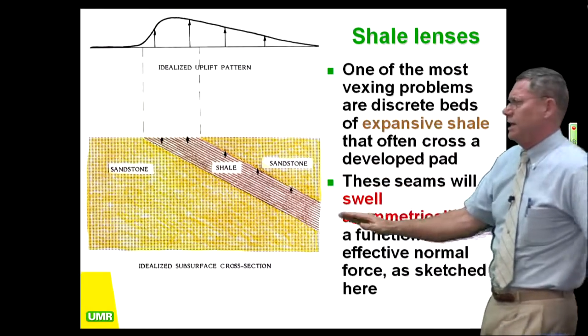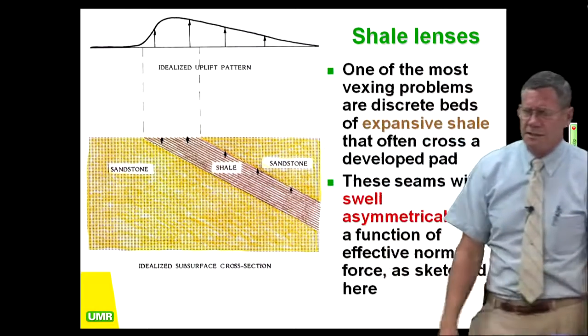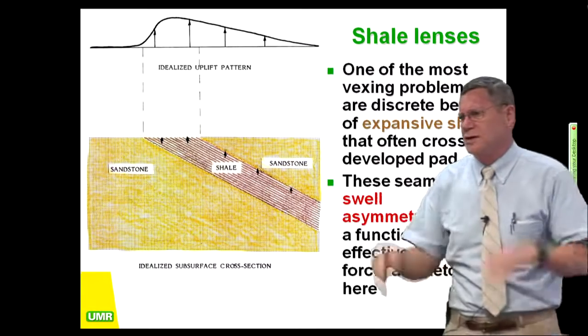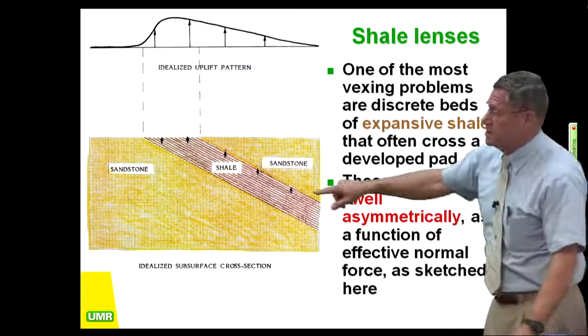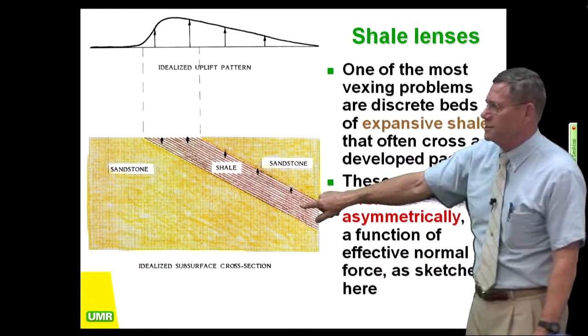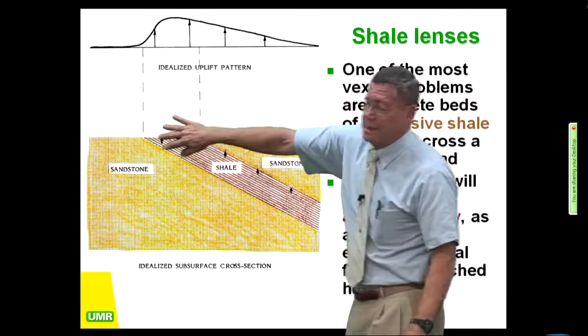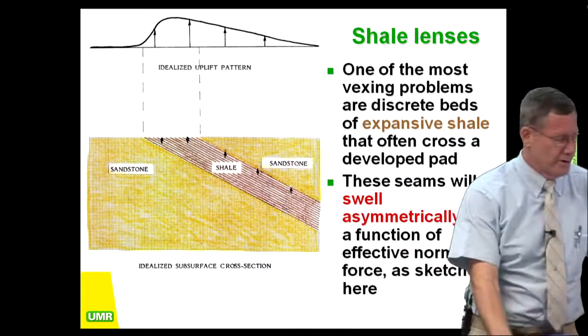So here's where you really got to have the engineering geologist out there with his eyes screwed on saying, hey, we got little shale stringers in here, 3 inches thick. The soil engineer's going, 3 inches, so what? We'll be putting piers through it, no big deal. Guess again, it can be a real big deal. If you got any smectite clays in here, you're hosed. You have to over-excavate down about 6 feet and backfill this with something else. 6 feet's a minimum, or it won't work.